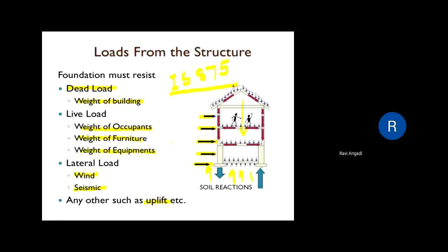Earth pressure produces a lateral force again, like the wind force is acting. The earth pressure is also acting because the foundation is buried inside the soil. So here the earth pressure produces a lateral force against the structure below the ground surface or a filled surface. The earth pressure is determined using the lateral earth pressure theories, Rankine's theory, passive earth pressure, active earth pressure. Those theories are to be used and the earth pressure calculated and suitably applied for the foundation.